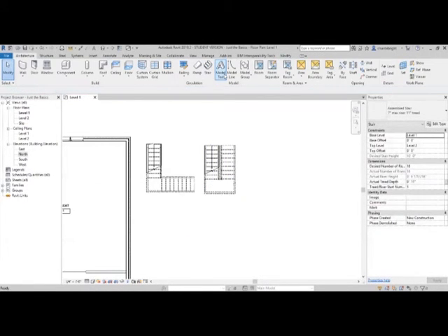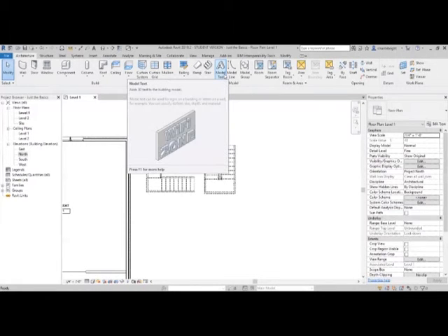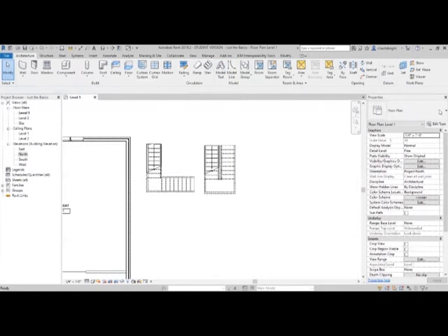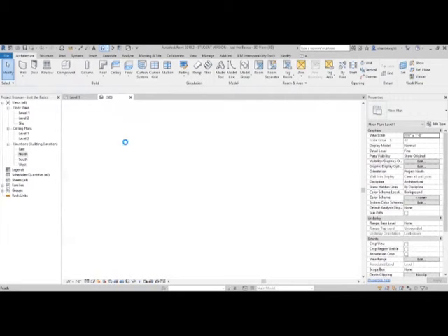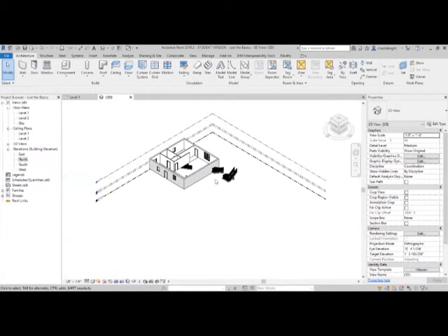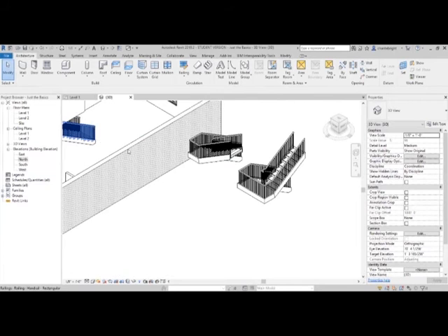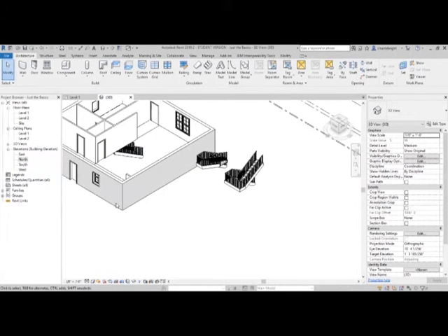So you can do very many different shapes and types and sizes and directions for your stairs, but they all run off of the same basis where it takes your 7-11 calculation in, if that's how you have it set to. It takes your level lines into consideration, and then it does the math and puts everything in from there. And if I were to go into 3D, you'll see that this is a full-blown stairs in this project. It's just right now it's going nowhere. So there's even my stair that I had before.